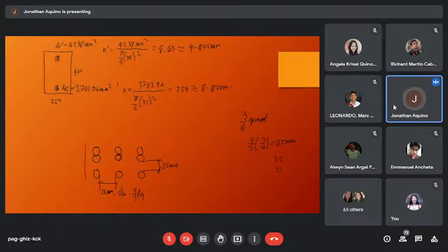So if we have 250 millimeter, then we have stirrups 10, then we have a concrete cover of 40. The clear distance C is equal to 250 minus concrete cover on both sides of the beam, 2 times 40. Diba? Dalawang side. Minus dalawang stirrups, dalawang 10.